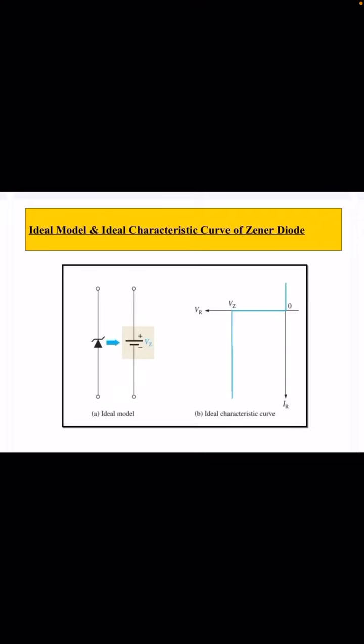Ideally, what is considered for the Zener diode, as I defined the impedance, delta Vz over delta Iz, is that there is no change in delta Vz, but there is a very high increase in the reverse current. So it's 0, meaning there is no change, but practically it is not the case. The case is different.